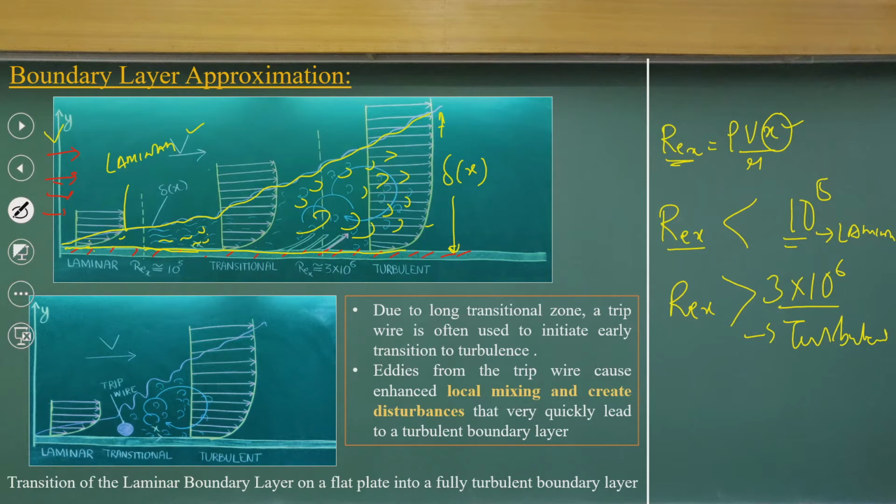and we can understand how much complexity there will be. So, mostly we are looking at the characteristics of laminar flow, and what the boundary layer thickness is. As I discussed, this is the thickness we are defining, where the u component of velocity is close to 0.99 of the free stream velocity. That is, 99% of the free stream velocity. To simplify the problem, we look at the locations where the velocity is close to 0.99 of u.